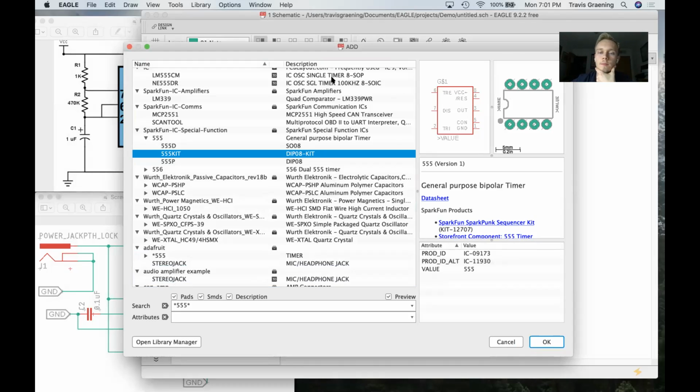Yes, through-hole components, which you'll see in our through-hole soldering workshop or later this quarter. That literally means that there is a hole through your PCB that you stick your parts into and then solder it to. Surface mount, on the other hand, which we'll actually be having another soldering workshop for next quarter, means that the part is just on top of the board, on top of the pad. It doesn't go through and you have to solder it directly onto the board.